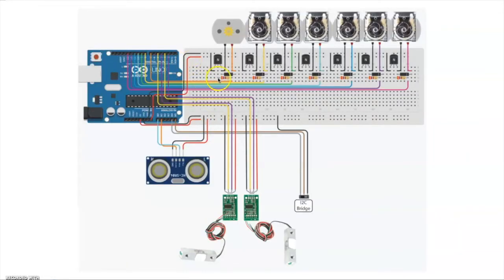Arduino Uno has multiple pins which allow us to connect actuators and sensors. The pumps are run on 9 volts by using a transistor as a switch, allowing for controlled power supply to all motors. The two microcontrollers are connected by an I2C bridge, which we will go in depth on.